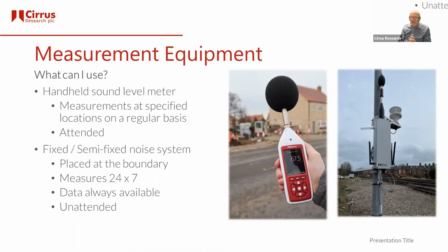You can take readings at these measurement points on the boundary on a regular basis, and that's what we call attended monitoring. One of the advantages of attended monitoring is you're there with your ears listening to the sound at the same time you're taking that measurement. So if you get a high reading, you can instantly look around and say, well, that's that breaker over there that's causing that, or it's pile driving or something like that. So you've got that instant link between the level that you're measuring and what's going on on the site.